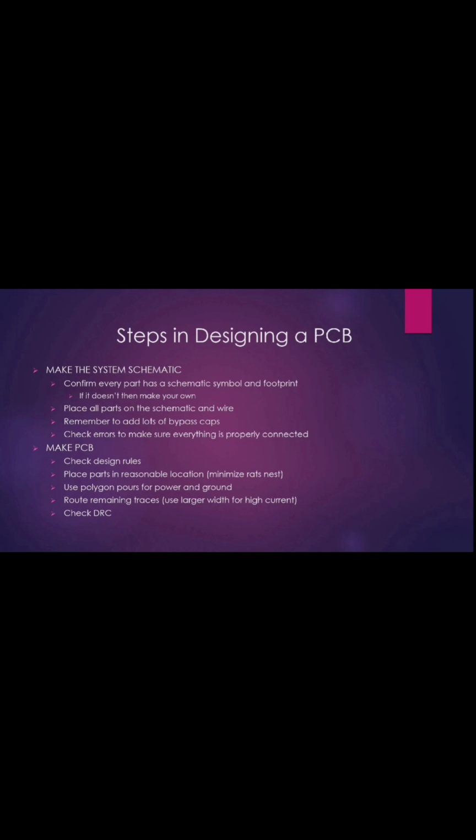If it was done perfectly, then comes the PCB part. For the PCB design, we use an insulating material as a plain mechanical support, which is also known as a plain board, and clearly check the design rules before entering a new project. After confirming, place each and every part on the schematic sketch and make sure that we make separate polygonal pours for power and ground. Just diagnose it once to check whether there are errors or not.